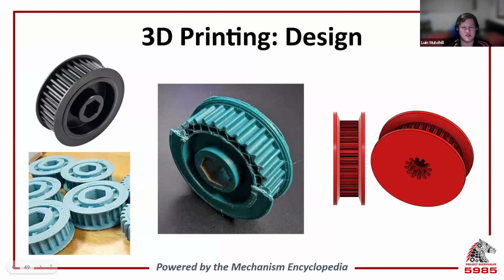To fix these issues, it's best to generate a pulley in your CAD software of choice. For example, in Onshape, you can import configurable pulleys using the MKCAD app. You could also modify the step file of the COTS pulley to remove the cavity and add a thicker flange, but it can be a time-consuming process.